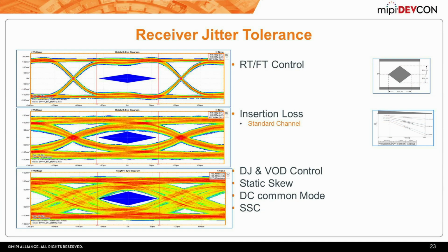So I thought I would just describe the most complex test in receiver testing, as you might all know, the receiver jitter tolerance test. It kind of uses all the parameters, right? Try to use all the stresses needed, which is accommodated for in the design, and try to create a stressed signal with which you want to test the margin the receiver has or whether it performs well.